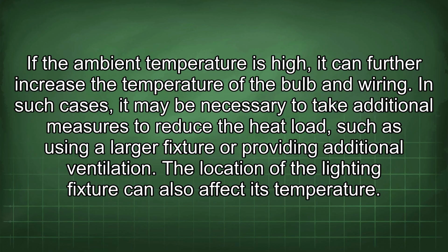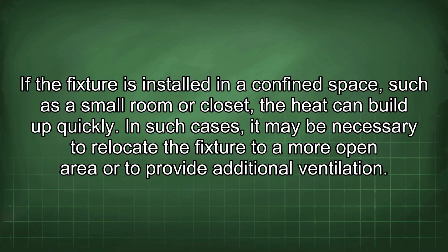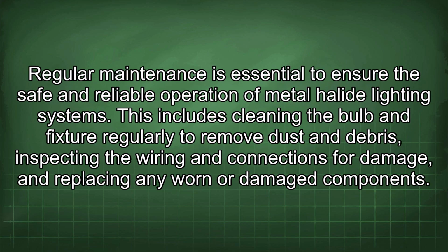The location of the lighting fixture can also affect its temperature. If the fixture is installed in a confined space, such as a small room or closet, the heat can build up quickly. In such cases, it may be necessary to relocate the fixture to a more open area or to provide additional ventilation. Regular maintenance is essential to ensure the safe and reliable operation of metal halide lighting systems.